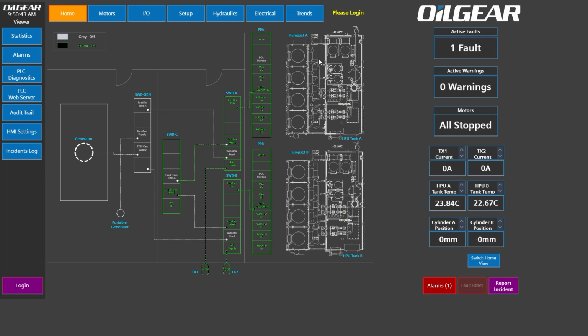So what they did is they then put an invisible button here, which as I hover over it, you can see it highlights. An invisible button here to just push that username and password into the login. So you get logged in as the highest security level, and then again, logged out. Now, they did this whilst I was off site. I got back on site and I was like, what the hell are these guys doing? Like, that is so dangerous.